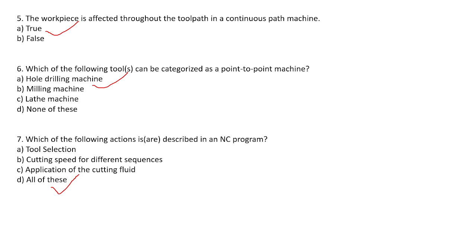The MCU interprets the G code and executes the corresponding movements and functions to produce the required part. So that's how it works between the G code and the MCU.